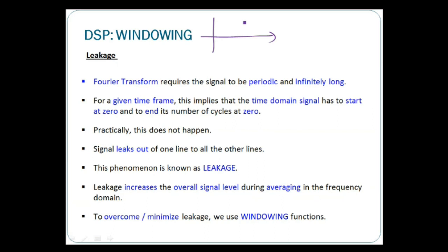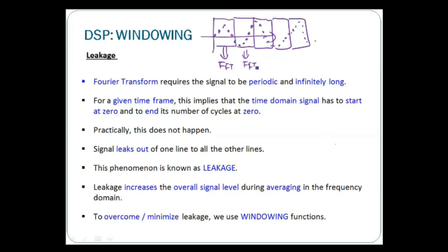You still remember we have a signal in the time domain, samples, and we select a fixed number of samples, which is our block size, to process into the frequency domain. Every block is sent to the FFT to get one spectrum.